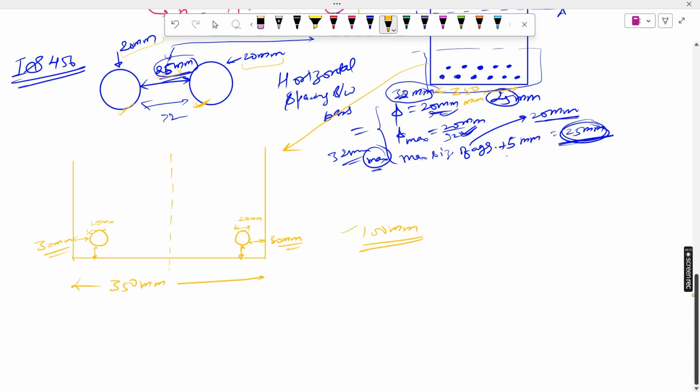Okay, so how much spacing does it occupy? 100 mm. Now we have the remaining spacing as 250 mm, and if I put 1 bar, I have to maintain the distance as what? This is 25 mm again, and that will occupy 20 mm again, and here I put a bar also, so this is 20 and this is again 25. So what is the value occupied? 25, 25, 20, 20. So 25, 25 is 50, and 20, 20 is 40. So it becomes 190 mm, and we have just put the 4 bars.